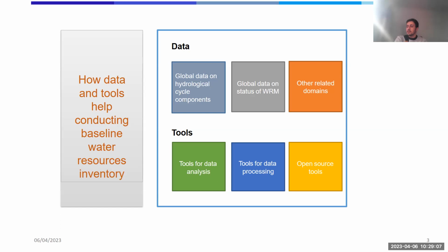These can be mapped and analyzed to understand the spatial distribution of water resources in a given area. Also, there is the remote sensing that we always mention. Remote sensing techniques, such as satellite imagery, can be used to monitor water resources, such as changes in water level, water quality, and land use. This also helps to identify trends in water availability and usage over time.